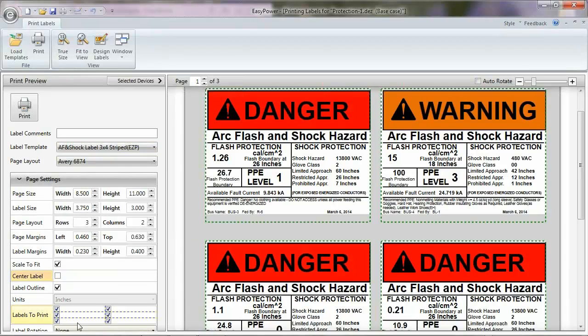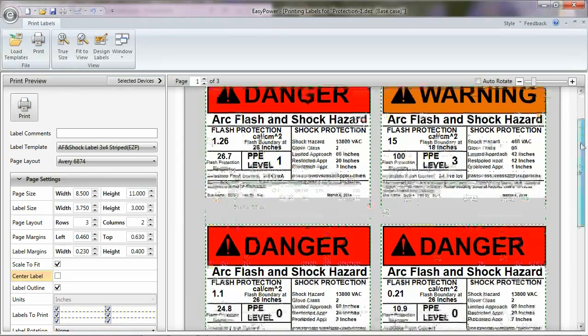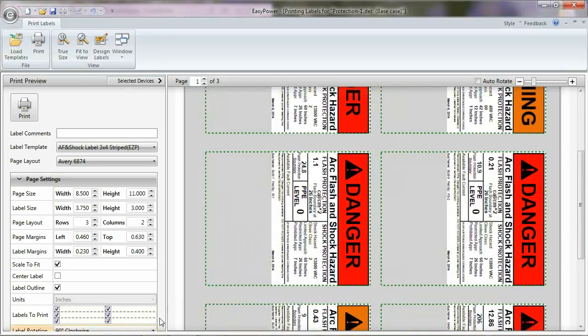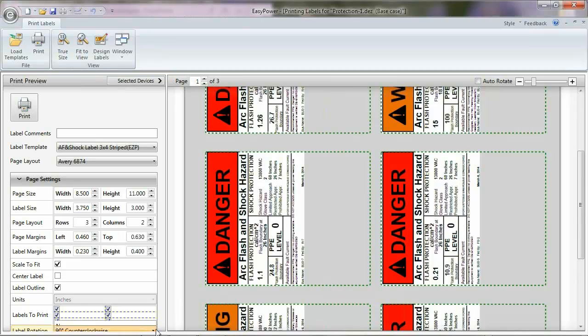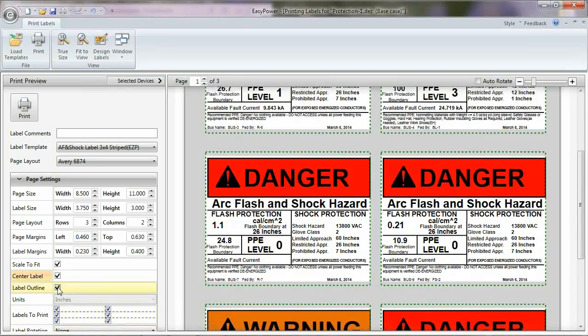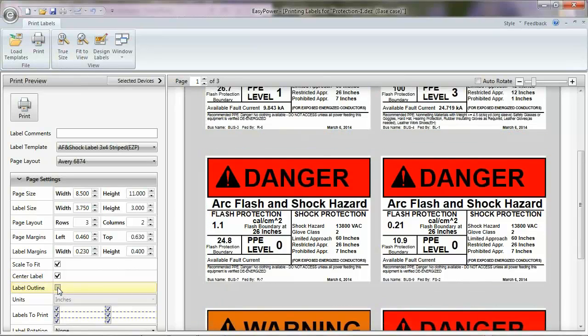And having a little bit of trouble here on the 720p because of space requirements, but you can also define the label rotation down here: 90 degrees clockwise, 90 degrees counterclockwise, or no rotation. That's more or less dependent on your style, the size of the paper that you're using, and the labels.